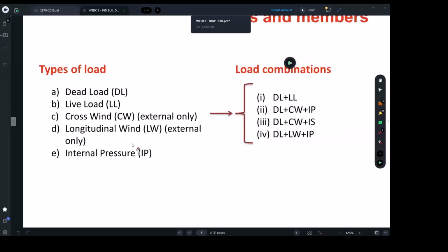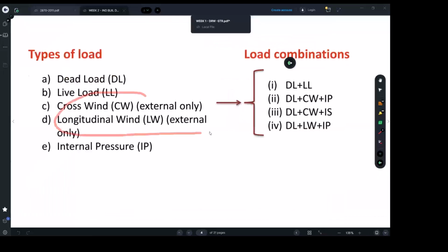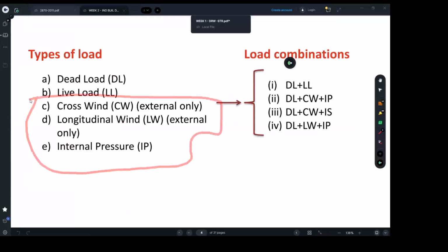However, in the buildings we're talking about, industrial buildings like those warehouses, the portal frames, wind load is very sensitive. Usually it can exceed dead load easily, because even the dead load, as we said, is just a sheet, and the sheet load is very light. It's 40 kilograms per square meter, the weight of a sheet. The steel sheets which sit on the purlins are not heavy at all. So wind loads, which are covered in points C, D, E, are all to do with wind load.